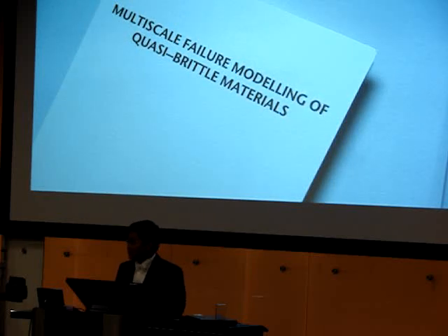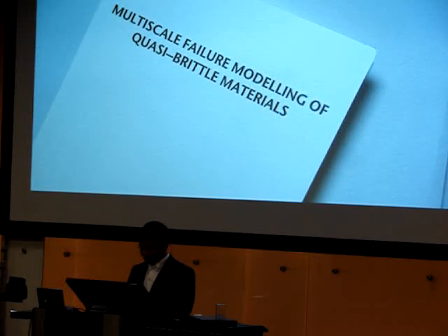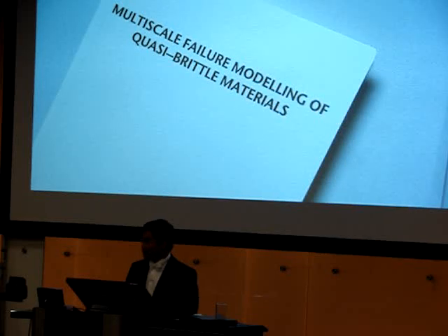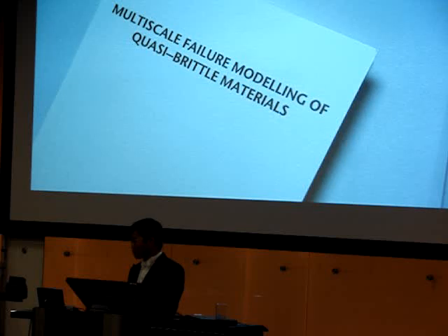So what I'm doing is the transition from a localization band to a macro discrete crack, and your question is just the opposite: from discrete microscopic cracks to a macroscopic band. That's correct. And I think it's possible. At the microscopic scale, we model discrete cracks, for example with the partition of unity method.